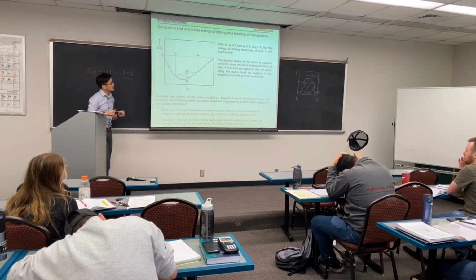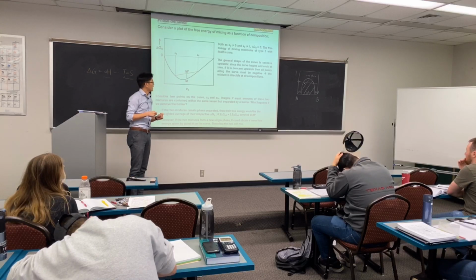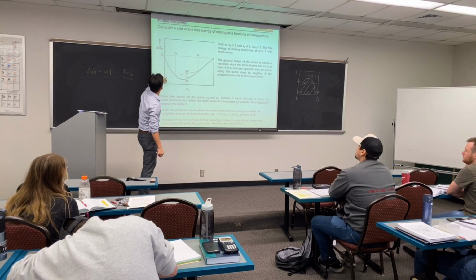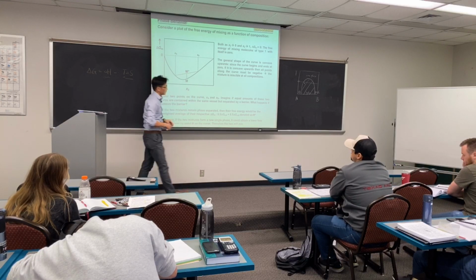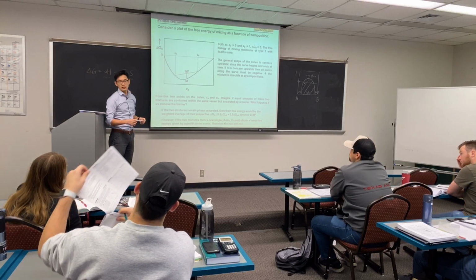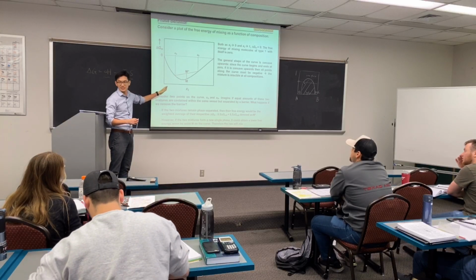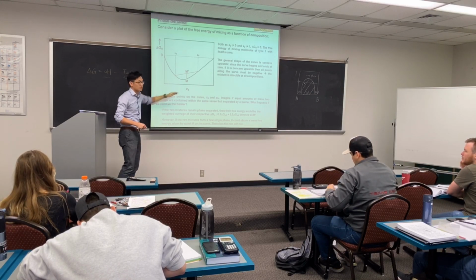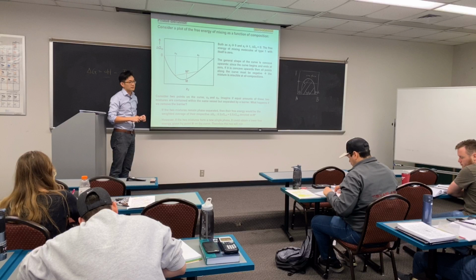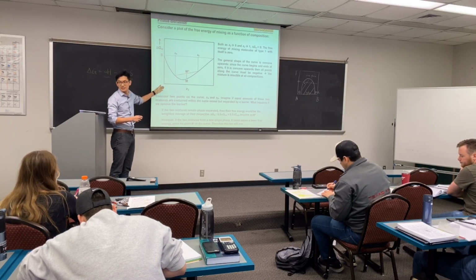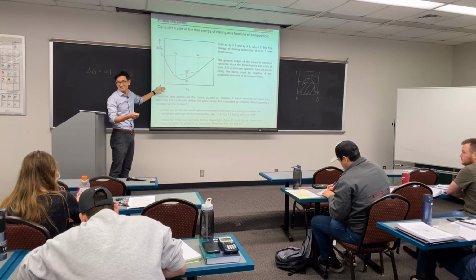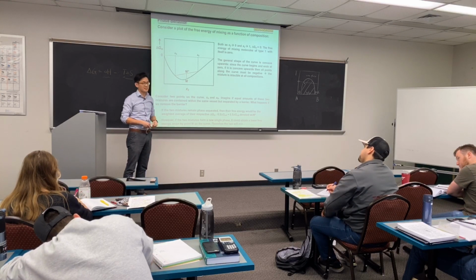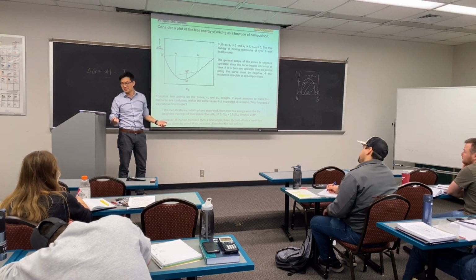Now the next question is even more interesting. Let's assume we have a generic phase diagram that looks like this. Vertical is delta G, this is X2, the volume fraction of X2. This is not a phase diagram, okay? It's different. It's just a free energy plot against different X2. Everybody can imagine how you get this? Flory-Huggins equation. You know chi, you know temperature, you know the blend ratio, boom, everybody can do it, right? We just had a quiz.